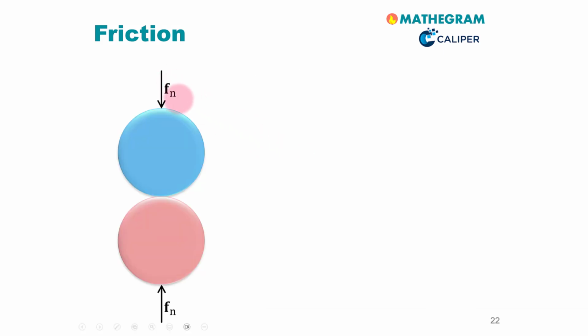So let us consider now a simple situation where we have again two particles. We load them with a normal force Fn here, same as before. The normal force at the contact here can be modeled with, for example, a linear spring dashpot model. Let us now assume that we apply a lateral shear force and prevent the rolling of the particles. Particles are not allowed to roll. Also, let us assume that we are not moving essentially, we are very slowly moving only in the worst case. So the time derivative of the momentum mv is 0, meaning that these two forces globally must be the same.